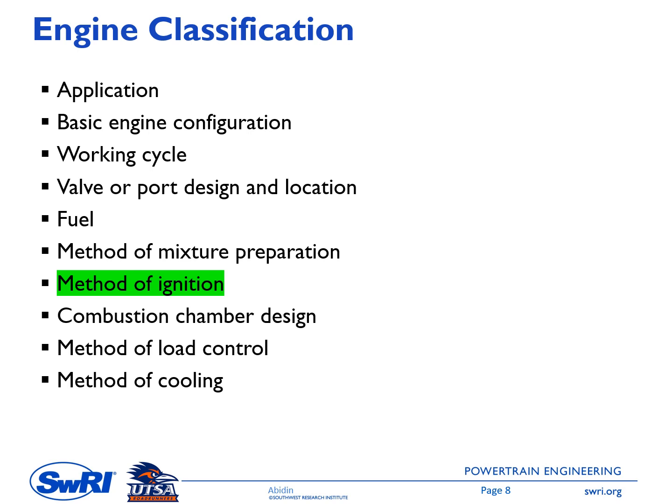So we have a gasoline engine, we have diesel engine, we have natural gas engine, might be also engine with methanol in the future. Can be classified by method of mixture preparation. So in this case, we have carburation. So this old engine, or even your lawnmower engine, they still use a carburetor to mix air and fuel before entering the engine. So it can be a fuel injection into the intake port. It's called PFI, port fuel injection, or it can be a direct injection to the cylinder. So you have GDI, gasoline direct injection.